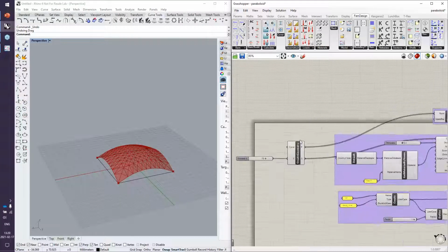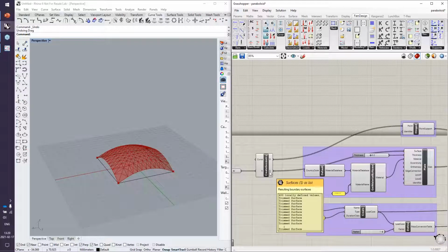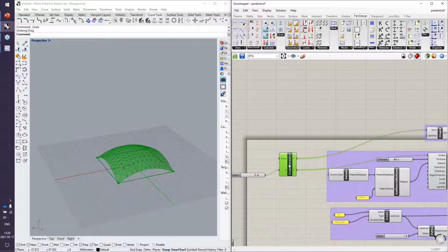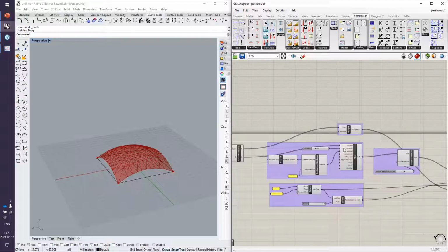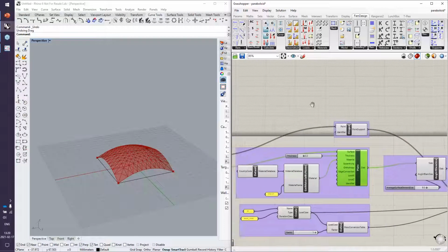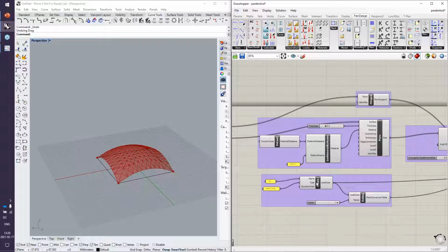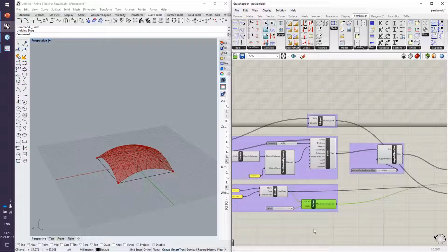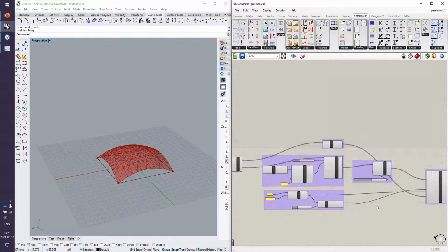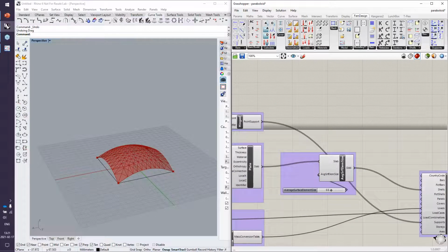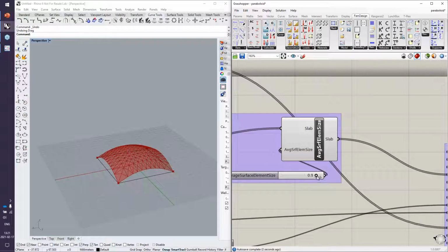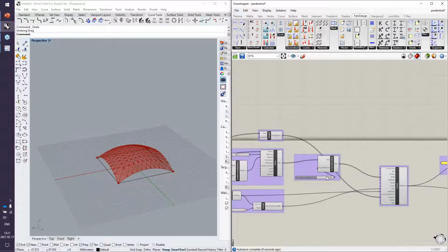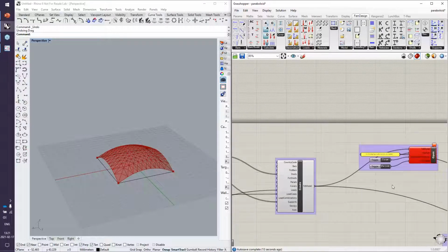So when we've created the geometry we want, I can quite easily get the points and surfaces out of this geometry with a cluster I made here. And on top of those points and surfaces, I can create my point supports, my plates with some sort of material, I can create a load case, and in this case I also create a mass conversion because I'm going to do a frequency analysis later on. I can use the toolbox to set the mesh, etc. So I think 0.5 is probably, I'm going to use a quite large mesh here. That's probably not accurate for design, but I want this to run a bit faster because the model is quite big.